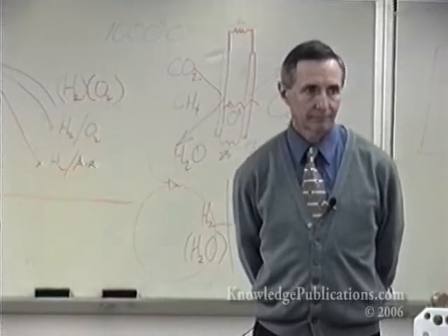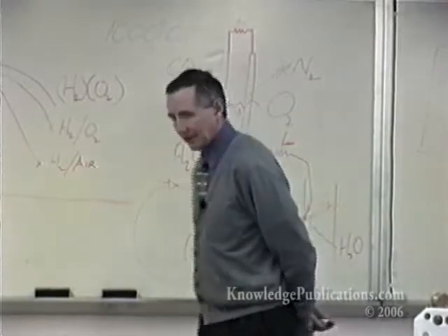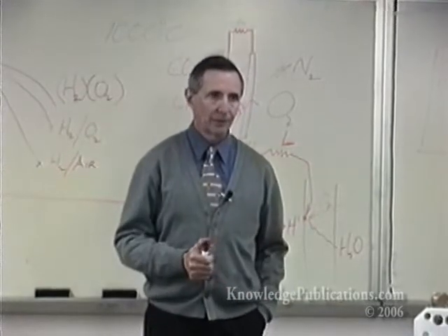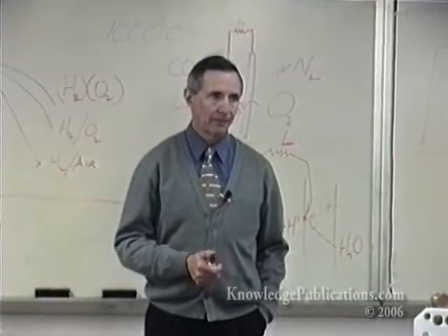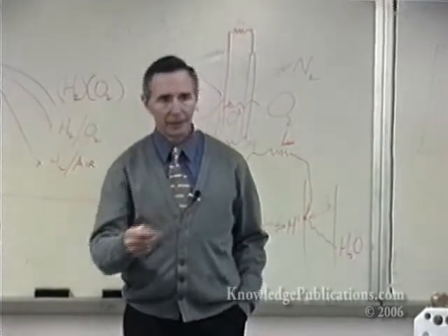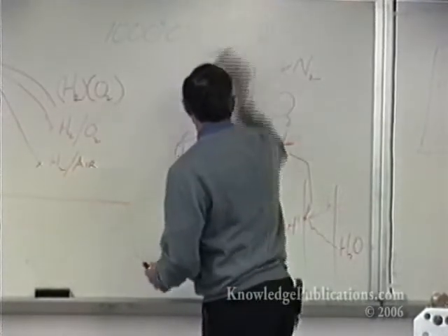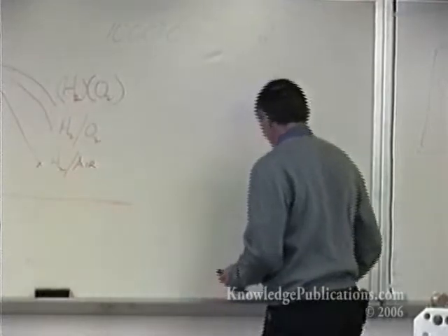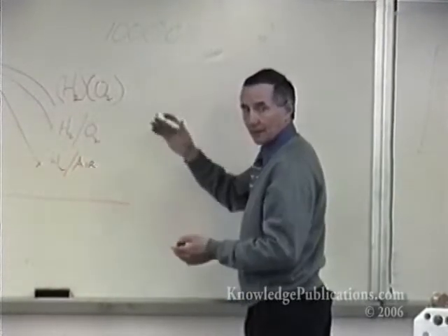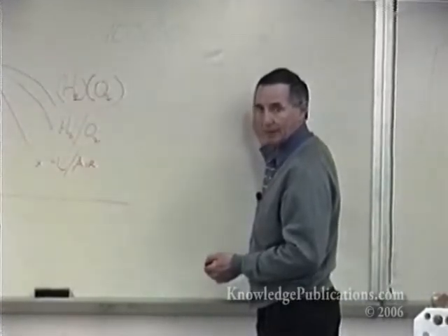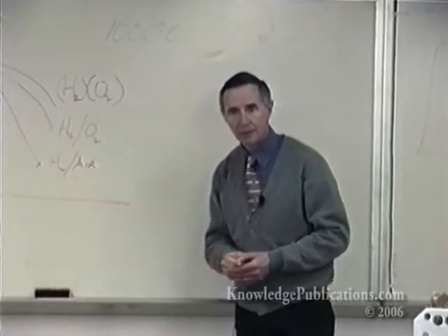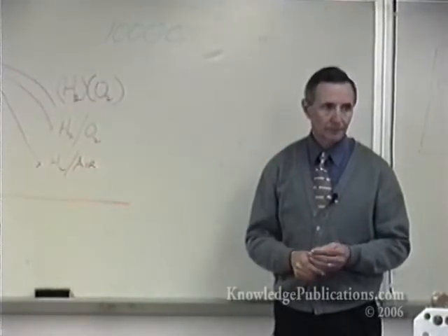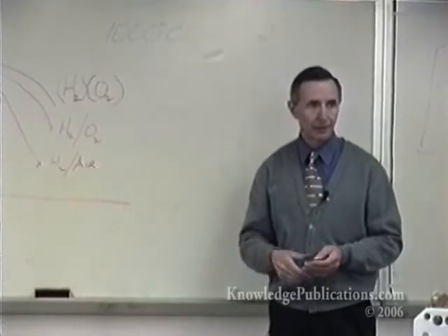How is that moisture thing dealt with on these fuel cells? Not this one here, but if we wanted to get a bigger application than what we have in this demonstrator, if we wanted to run, for instance, a camera or a television or a radio for your home, we'd build up a stack of these. We'd build up a system of unit cells like this, in series connection. So we would build up however many volts we wanted, such as a 12-volt system. We might have 20 or 30 unit cells like this, so that they could produce 12 volts at a current level that they were able to sustain.